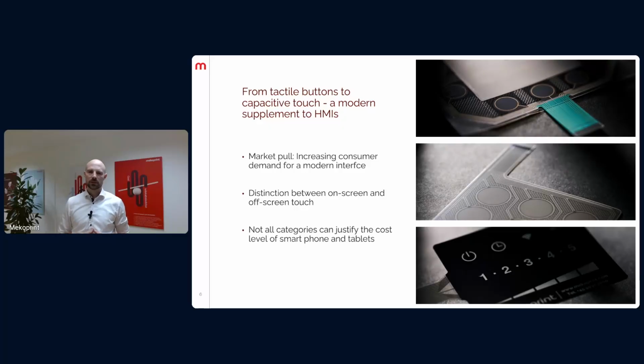Henrik will come back to this later, but these would be sensors that are typically printed on flexible substrates like PET. They typically use inks like silver, carbon, or PEDOT, from which it is possible to create either opaque or backlit single buttons, sliders, turn wheels, or whatever other button technology would be required.